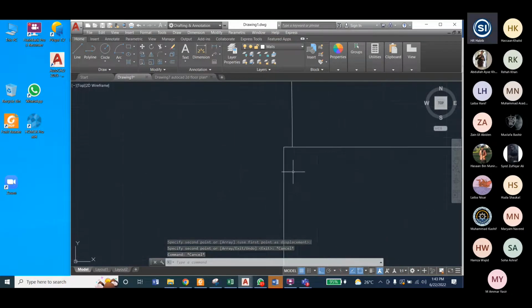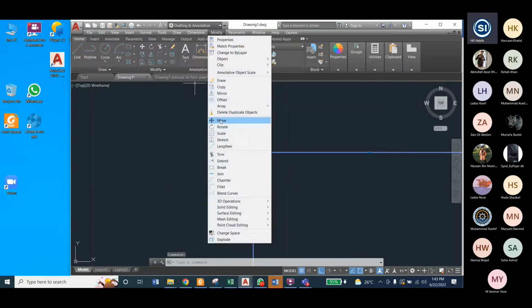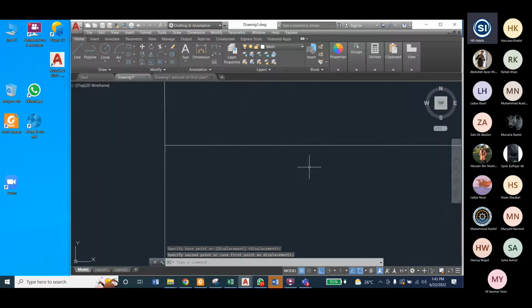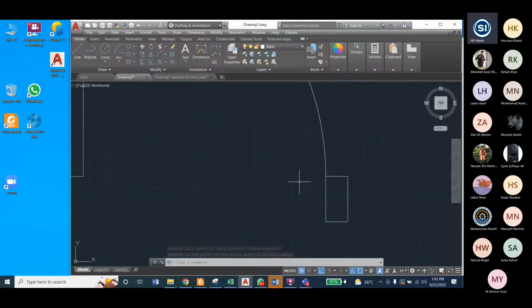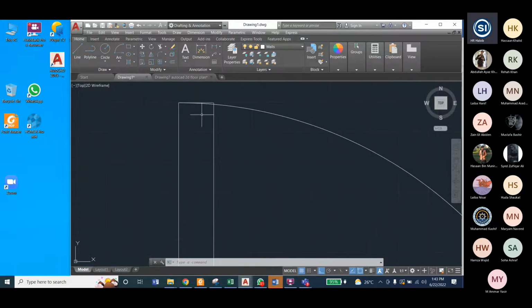And it is not exact, you see, sometimes this error will appear, so it is not okay. So just click this one again, select the base point and move it to the end of the curve. Now it is okay. Like this you can zoom in and see whether everything is going okay or not. Now our door is done.